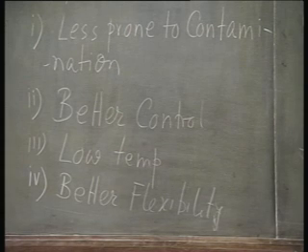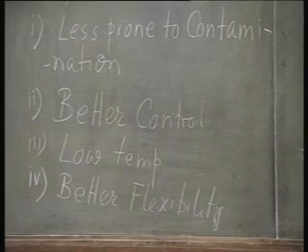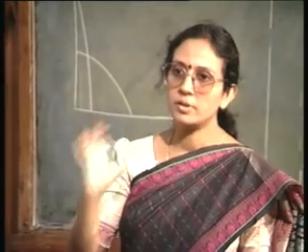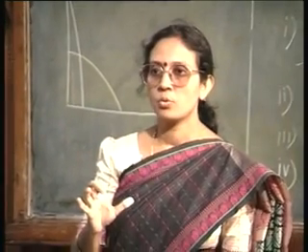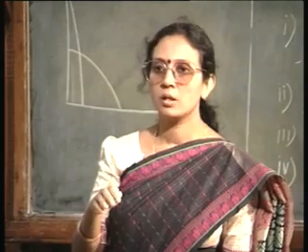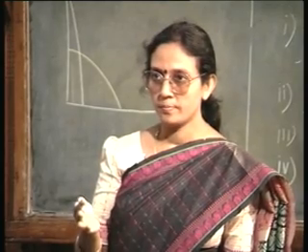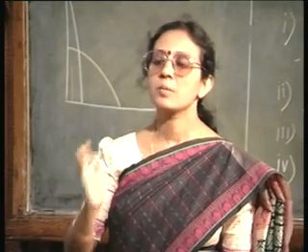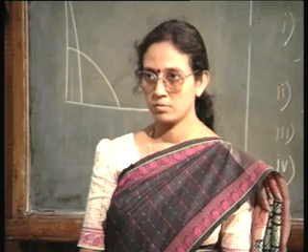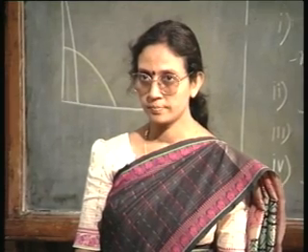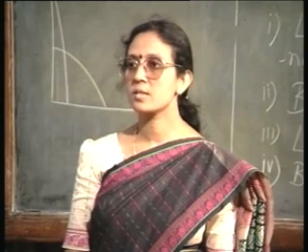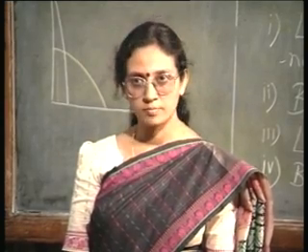Another advantage associated with ion implantation is this. See, in a diffusion, you are being governed by a set of rules which are, let us say, in equilibrium. That is to say, your surface concentration is governed by maximum the solid solubility limit, isn't it? The entire diffusion process is governed by the concentration gradient.